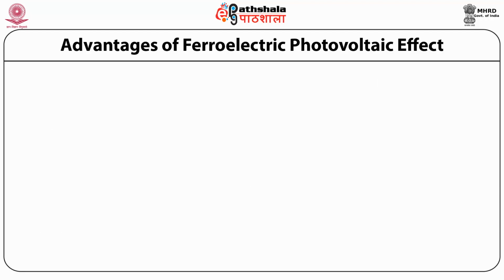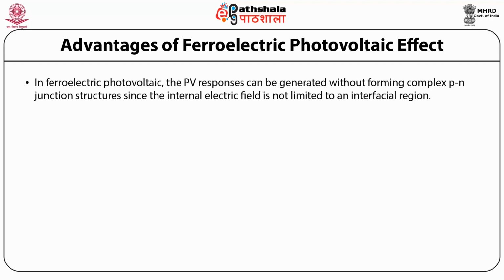So now let us discuss the advantages of the ferroelectric photovoltaic effect. First of all, in ferroelectric photovoltaics, the photovoltaic responses can be generated without forming complex p-n junction structures, since the internal electric field is not limited to an interfacial region.